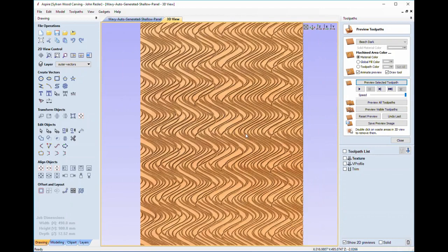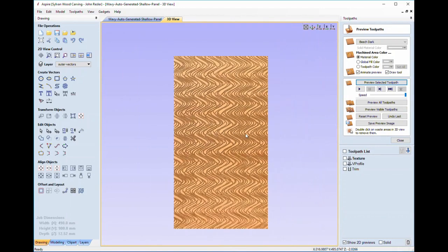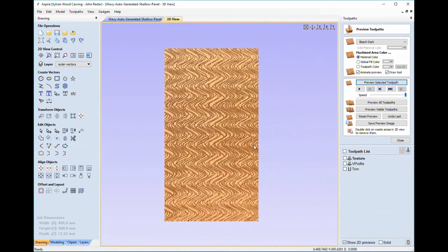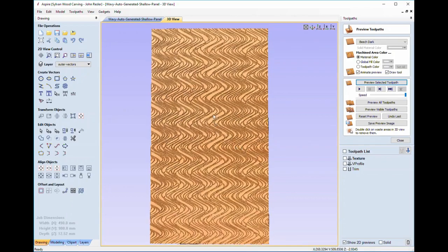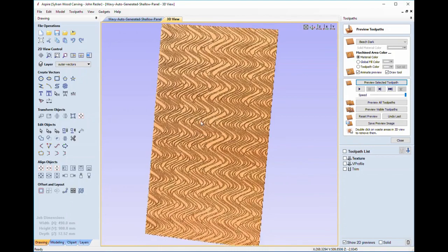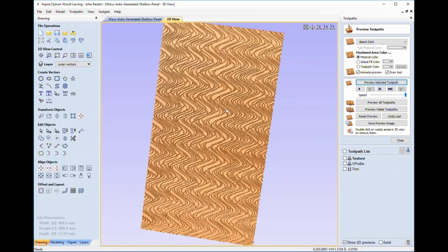Okay, now I have to tell you to be very careful if you decide you're going to do this with MDF, because my first setting was at 1/4 of an inch, and I think that works to be a little bit over 6 millimeters. Now because of that, the MDF was just gouged. It had nothing to do with the router bit or the speed or anything. It's just that I was cutting too much out and it wasn't going to look good, so I stopped it pretty quickly. Okay, so keep an eye on this. Let's remember this, and we'll go from there to looking at the picture of the finished product.